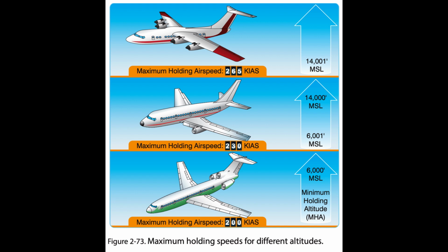limiting airspeed. If the holding speed limit is less than the pilot feels necessary, advise ATC of the revised holding speed. Also, if the indicated airspeed exceeds the applicable maximum holding speed, ATC expects the pilot to slow to the speed limit within 3 minutes of the ETA at the holding fix. Often pilots can avoid flying a holding pattern, or reduce the length of time spent in the holding pattern, by slowing down on the way to the holding fix.